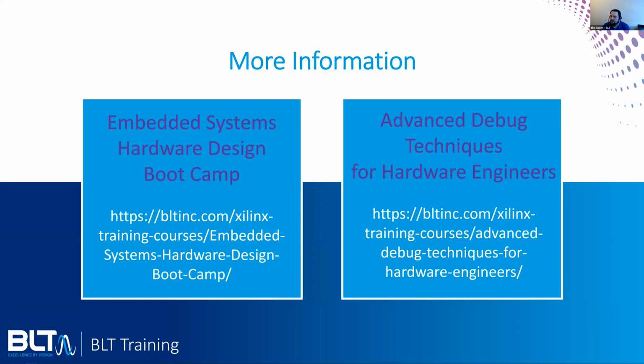There was a question earlier about whether or not this could be done with the Zynq 7000 series, and so yes, this can be done on a Zynq 7000 series, as well as another question on can you use this technique to debug during an interrupt service routine? And yes, you can use this during an interrupt service routine. Same thing with setting breakpoints. You should be able to accomplish the same thing here.